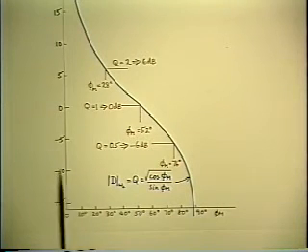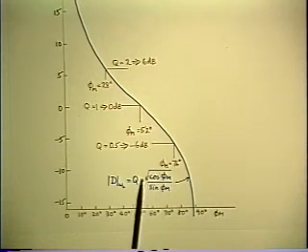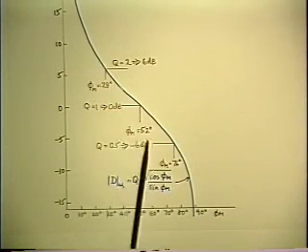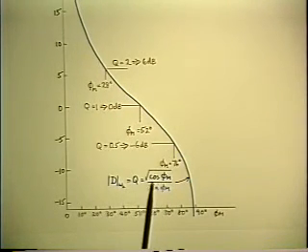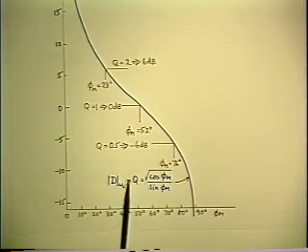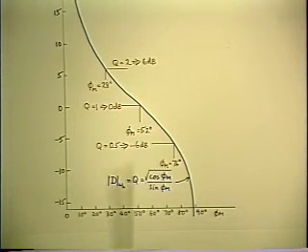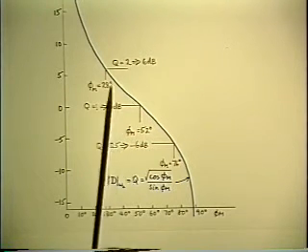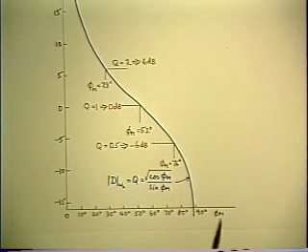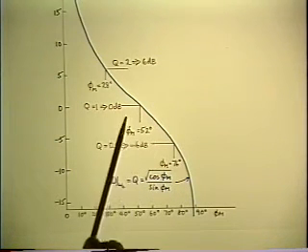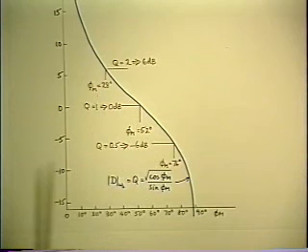This is a very interesting graph, because it gives you a quantitative idea of what a certain phase margin number really means. So the number of degrees means nothing in itself. What matters is the degree of peaking you're going to get in your closed loop response. And the important thing about this result is it's inescapable.